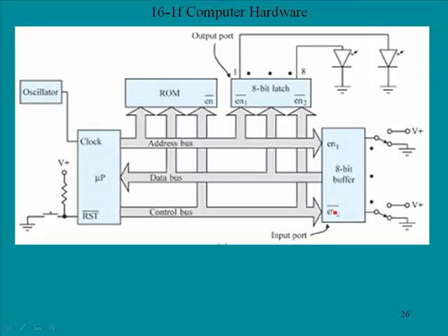And these are tri-state buffers, so in the event that you don't have the high and the low here, the outputs will just be high impedance, and the data will not interfere with other things that are going on in the bus.